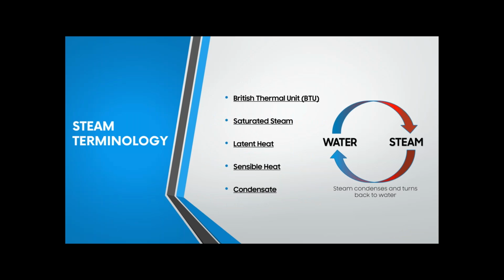All right, we're going to get into some of the basic steam terminology to help us as we move forward. The very basic is the BTU. The BTU, British Thermal Unit, is the basic unit of measurement for heat energy. The strict definition is that 1 BTU is the heat energy required to raise 1 pound of water at atmospheric pressure, 1 degree Fahrenheit. Now, saturated steam is a little tricky for newcomers to steam. Saturated steam is dry steam that is saturated with heat energy. It is not water moisture saturation.